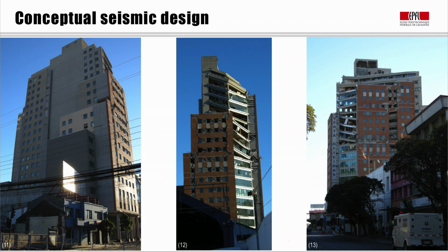An example of a building that has an asymmetric floor layout is the O'Higgins building in Concepcion that was damaged during the 2010 Chile earthquake. At the back of the building, there's a long, stiff wall. On the other 3 sides, we have many windows, and hence these sides are much more flexible than the back side of the wall. And this can introduce some rotation to the building.